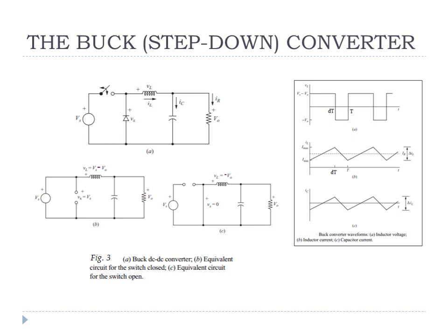The current through the inductor flows from I minimum to maximum value during the chopper on time, and it drops from I maximum to I minimum when the chopper is off. The capacitor current follows the same wave shape as the inductor current, because IL is the sum of IC plus IR. The average value of inductor current is the same as the average value of load current, so we represent it as IR.